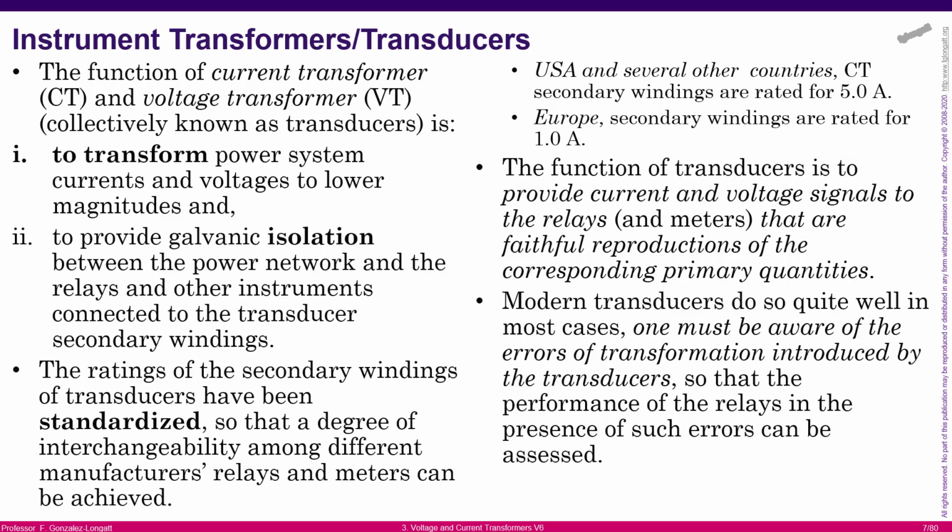On the other side of the Atlantic, here in Europe, we use standardized secondary winding, but the nominal current is only 1 amp. Okay, what is important to say is that those transformers, voltage and current transformer, the idea is that they must do the best effort to transform the signal, for instance, from short circuit faults of 100 kA to 1 amp,